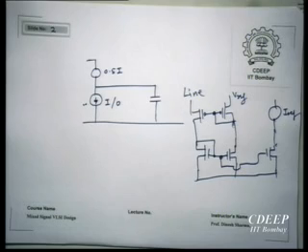In some sense, if you look at it, this is very similar to low swing voltage signaling, right? Because my voltage swing on the line is not exactly 0, because I cannot bring the input impedance exactly to 0. So there will be some residual resistance, at least the ohmic resistance of the wire and so on. So there will be some delta V. All that has happened is that now I can afford to have a delta V which is much smaller.